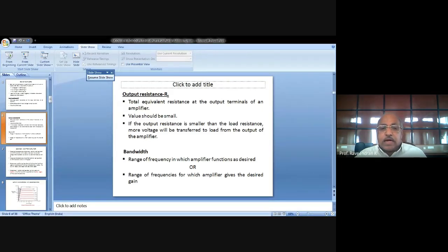And in this particular graph, where IB is equal to 0, the transistor is in the off condition, because there is no IC. So the transistor is in the off condition, and this particular region is called the cutoff region. And the region where VCE takes a very small value is at certain ranges of IB. When your IB is going on increasing, at a certain value of IB, the IC will be increased much, but accordingly the output voltage VCE will be reduced.